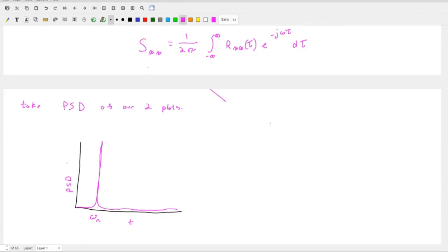So it's going to be voltage squared per hertz. You'll see that most people leave it off. The reason for that is it's really more of a relative measurement, right? It really matters where your peaks are and how big they are compared to other things. It's not a real qualitative measure. So voltage squared per hertz doesn't really mean anything.